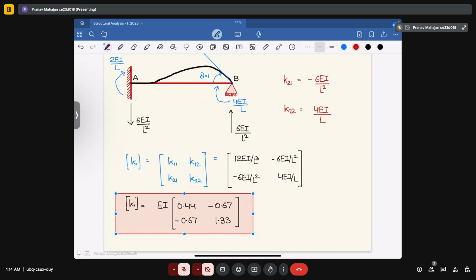This is the basic course of civil engineering, where we do the analysis of the loads at different points of the section. So we started with the analysis of statically determinate structures. How do you define a statically determinate structure? When the number of unknowns in the equation is equal to the number of available equations. How do you define the number of available equations? Generally, we define it to be equal to the number of equilibrium equations.